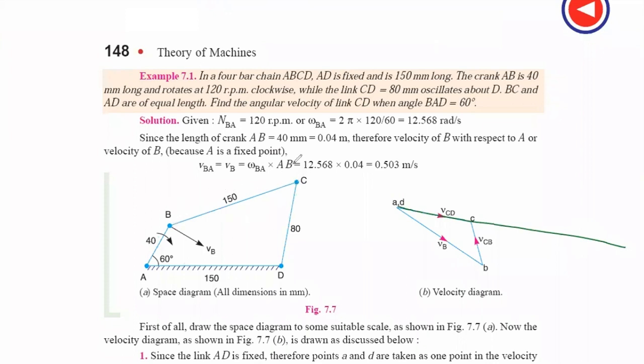C point will be located after the understanding of the motion of C with respect to B. So the C position would be perpendicular to the link number BC. That would be again 90-degree angle, na? And you need to write VCB, velocity of C with respect to point B. And that would be perpendicular to the link number CB. Correct? And see this thing that we are drawing that in upward direction. Na? If we will draw that in downward direction and that in backward direction, so they will not meet.